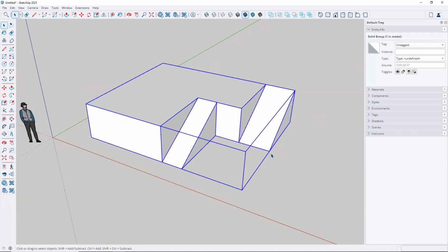So again, this is a very important, key concept in SketchUp to understand, and you'll hear me repeat this a lot at the beginning. Like we just made a surface or a 3D object here, group it. Triple click, right click, group. And you'll get used to that.